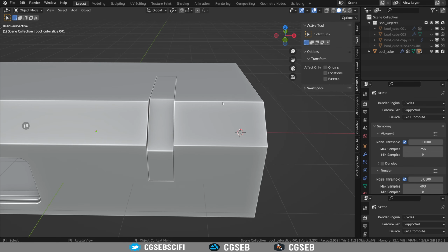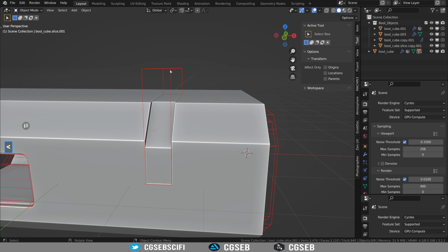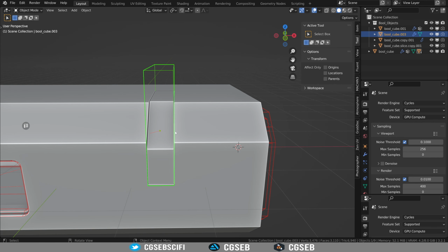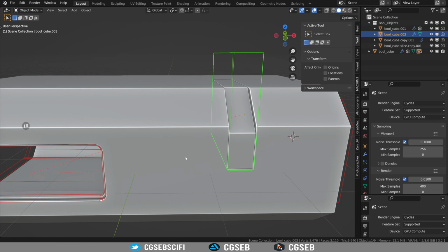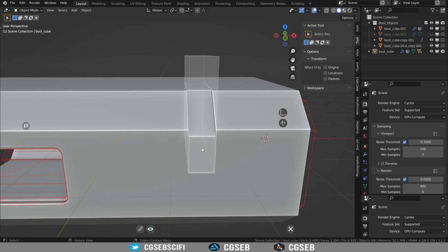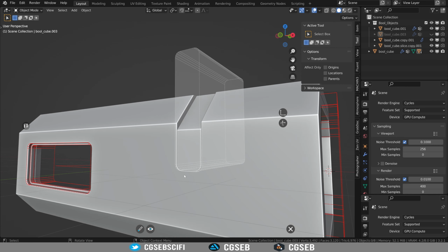So that's a cool technique that I really use in hard surface, and you can also mix up the round corners here and the straight line there. You can repeat these details by pressing F, edit, and then press B for bevel, and then add a small bevel at the bottom.